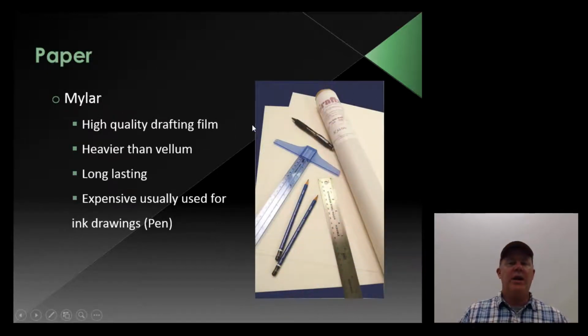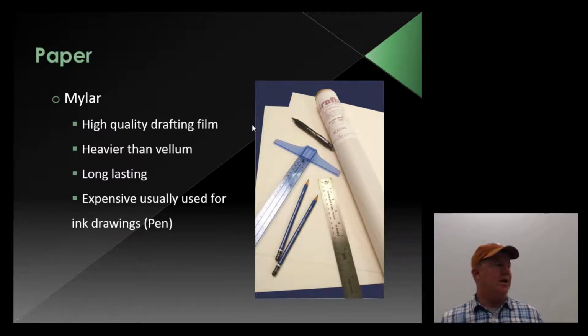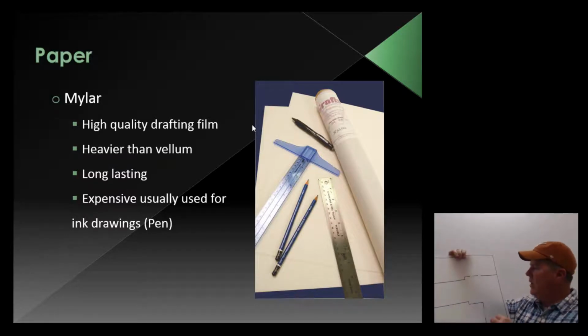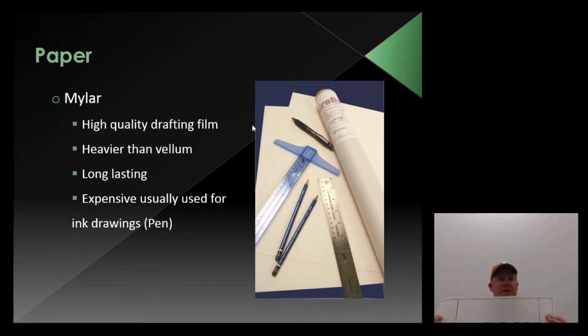But you can go to what we call Mylar. Now, I will get a sample of Mylar for you here in a second, but it is a high quality drafting film. It's heavier than vellum. It's long lasting. It's expensive. It's usually used for ink drawings, and let me get you a sample. It's almost like a clear plastic. But hopefully you can see here, it's more of a plastic film.